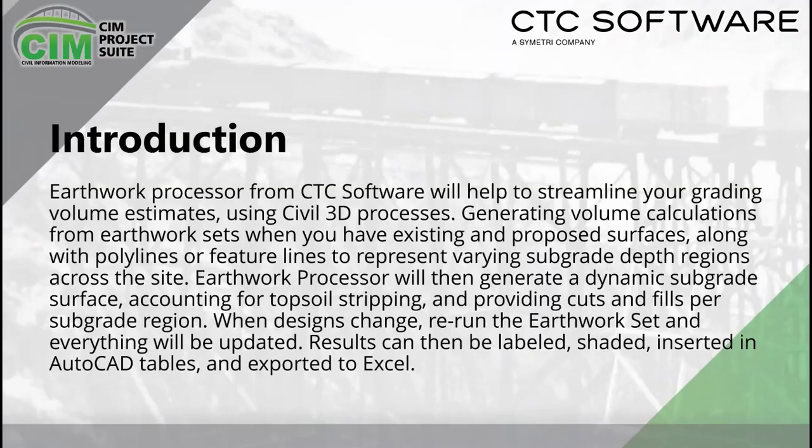It will then generate dynamic subgrade surfaces, and we can account for topsoil stripping at the same time and provide cut and fills per region. And if designs change, we simply change our depths and rerun it. We can also then export those to an Excel and also put an AutoCAD table right inside of the drawing.